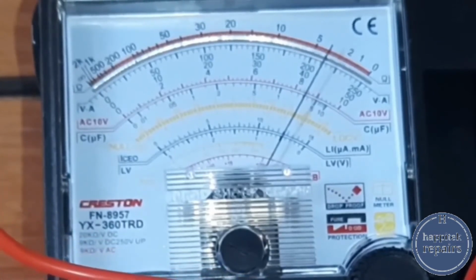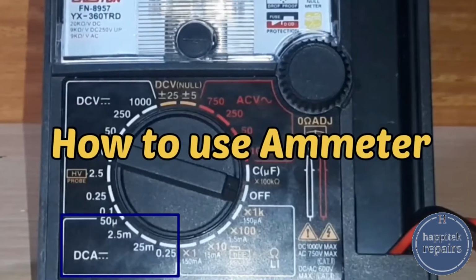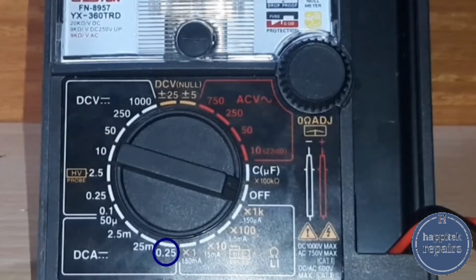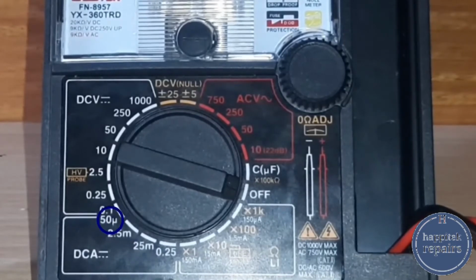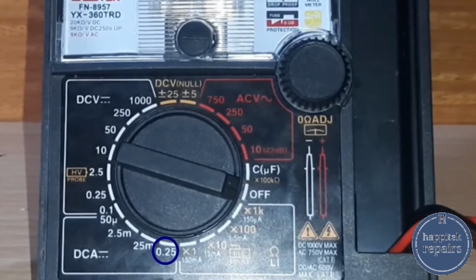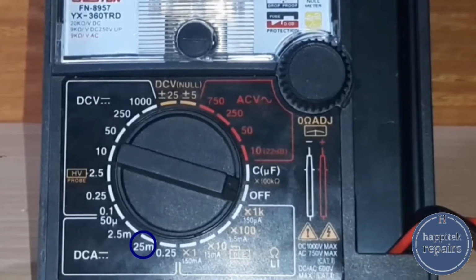For the DC ammeter, these are the settings we can use in measuring current: 0.25 amp, 25 milli, 2.5 milli, and 50 micro. If we use the 0.25 setting, the meter range we should look for is 0 to 250, multiplier 0.001. Set the meter to 25 milli.